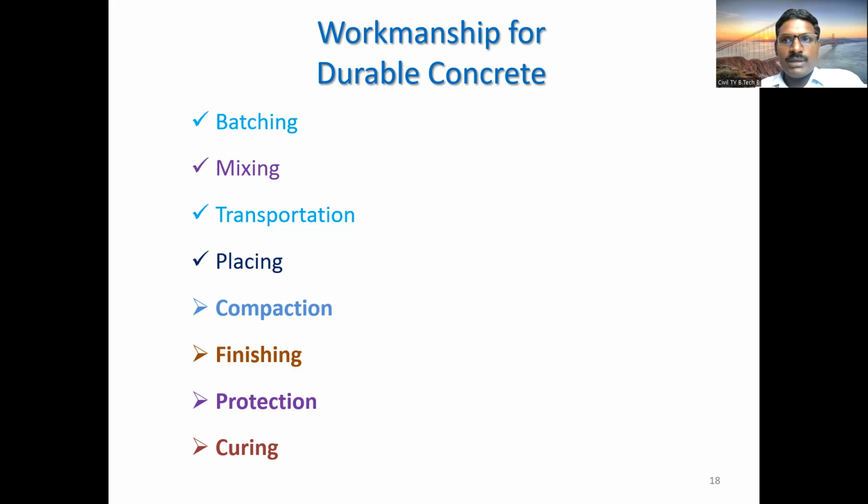In that structural component we place the concrete as per some guidelines for placing, as we have learned in concrete technology also. Then compaction. After placing, we have to compact the concrete so that we can reduce the porosity.